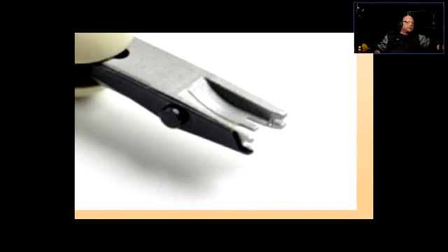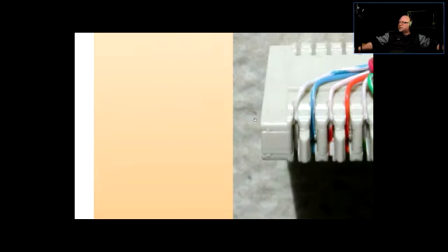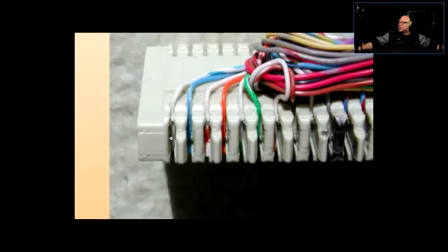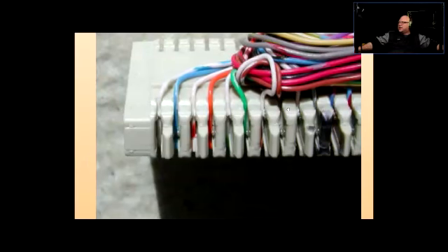It does have the element that pushes the conductor into the insulation displacement connector, and it does have a knife. In the BIX, this is the shape of the punch-down tool, and this is the shape of the knife, and the knife is a moving part. Once you punch it, there's a certain mechanism there that makes the knife go across and just cuts the wire off. So when you have those conductors inserted into those connectors, you put in the punch-down tool right here. It pushes the conductor inside the IDC, and it cuts off the unused part of it, and you get a nice and clean installation that way.